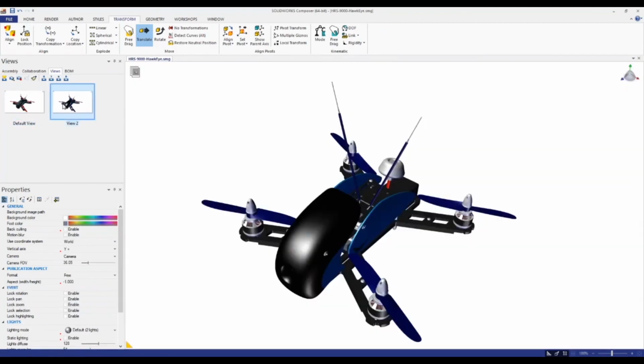And where this comes into play is when you update something. For example, say a change has been made in the SOLIDWORKS model, and we want to make sure that change carries through, so we update our Composer model. But the thing is, when that happens, because the SOLIDWORKS model is driving our Composer model, the SMG file, the neutral properties will get removed. They'll be overridden by the ones inside of our SOLIDWORKS file. So that means any neutral properties that we set will be replaced with the new ones.